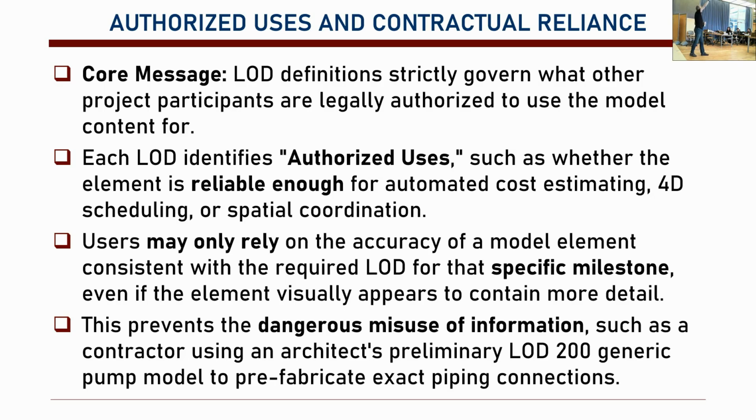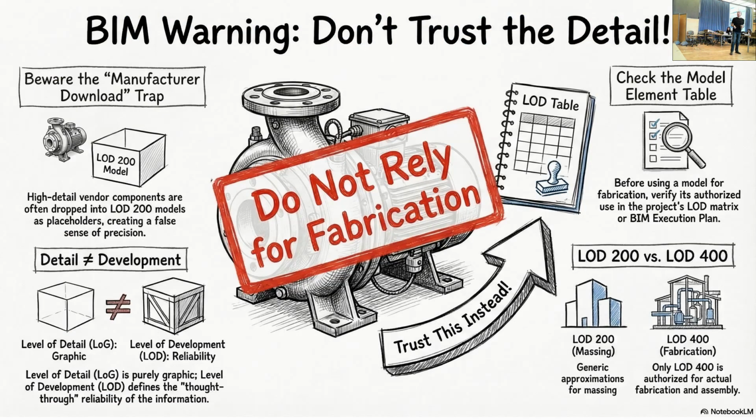So, if I put this and the contractor uses it for the construction process, that is misuse of information, and we don't want it. We don't want an LOD 200 model to be used for that kind of purpose. So, like that. Don't rely on it for fabrication. This is not enough for construction. Okay? Use it only as a space holder.